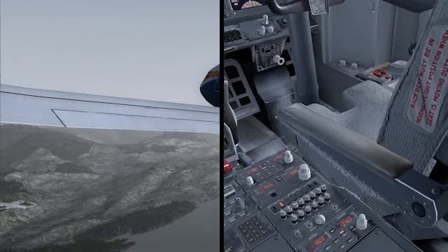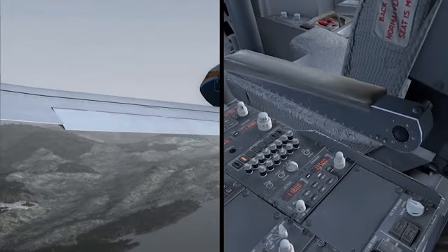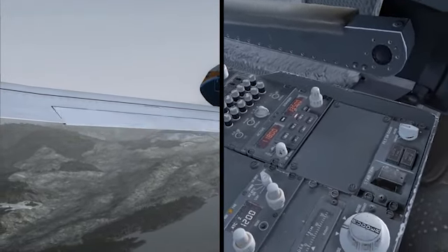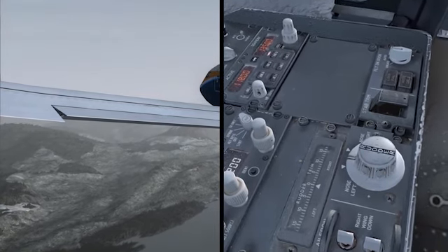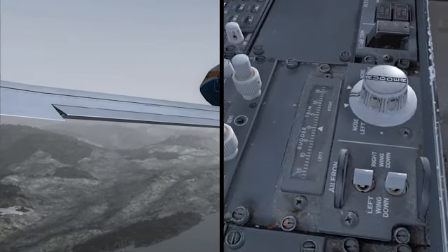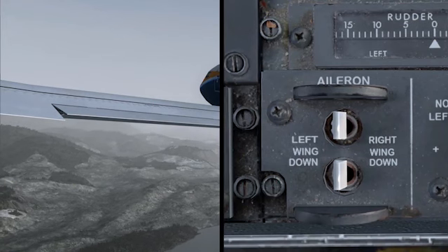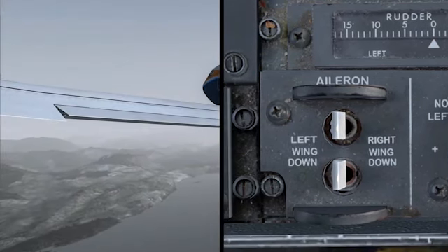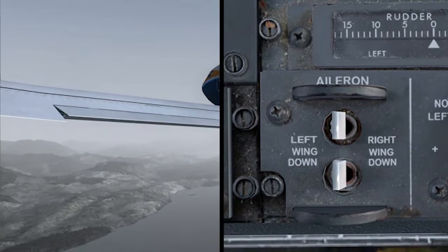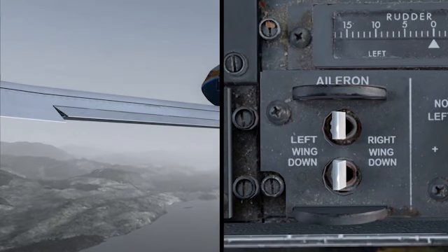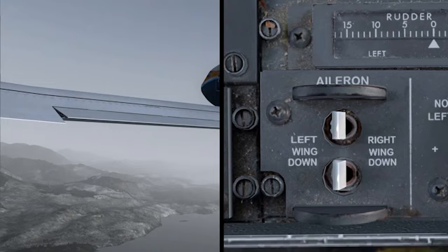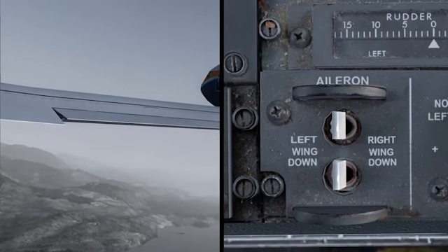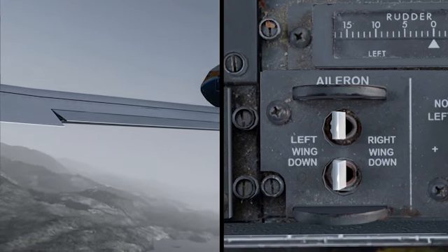Instead, 2 aileron trim switches are located in the aft electronic panel, and the aileron trim indicator is located on the top of the aileron control wheel. The indication is in units of trim, where each unit is equal to 6 degrees of control wheel rotation. The maximum trim available is 9.5 units, or 57 degrees, of control wheel rotation.